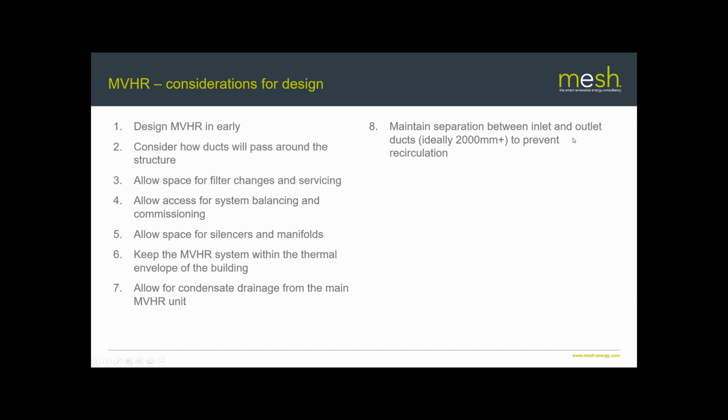Maintain the separation between the inlet and outlet ducts, ideally a couple of meters. You can reduce that a little bit, but that's just to prevent the stale air being recirculated back in with the fresh air.